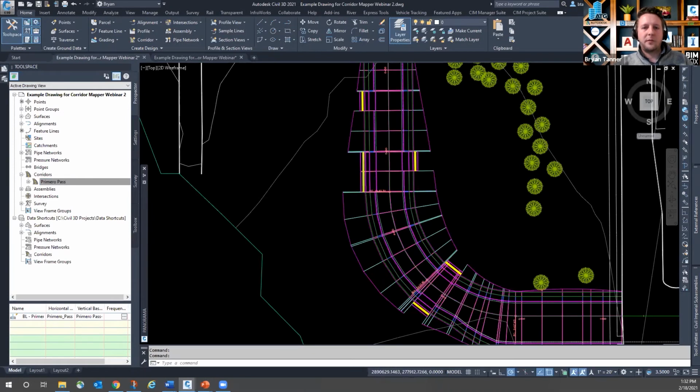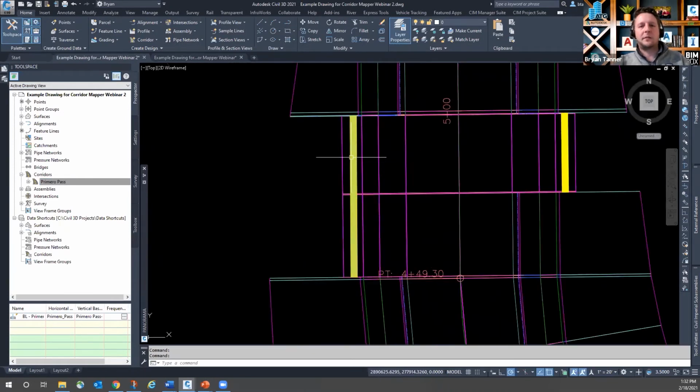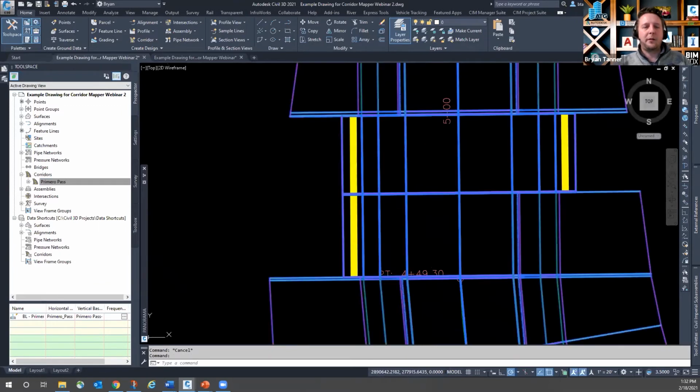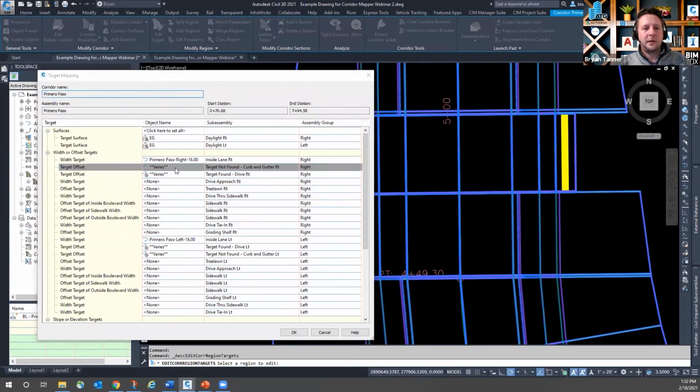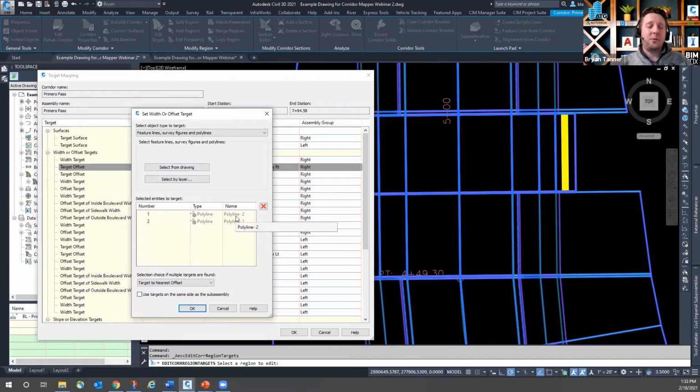Well, you saw it before, even if you weren't paying too much attention or didn't understand the significance of it, that each one of these polylines that's inside the targeting group has a name associated to it. Polyline 1, Polyline 2. And if you copy polylines, because of the database, they're going to have their own unique identifier, but copied polylines, you may end up with Polyline 1, Polyline 1, Polyline 1 as you copy those around. Not that there's anything inherently wrong with that. It's just how Civil 3D and the AutoCAD database categorizes that object inside the software. Call it a limitation, call it a feature. It's just what it does.